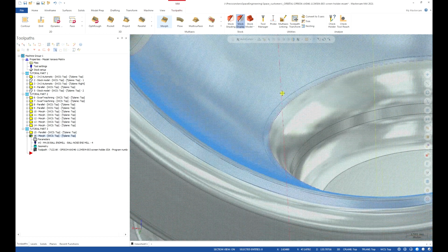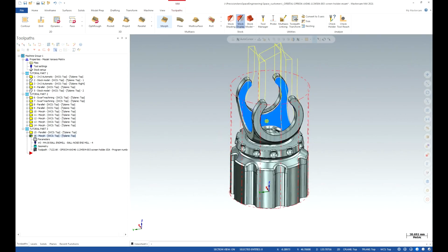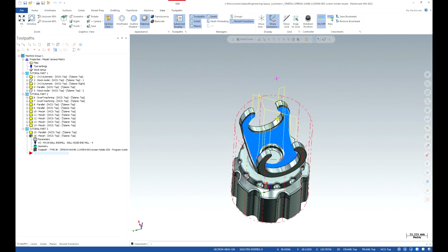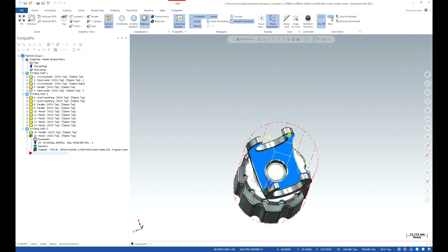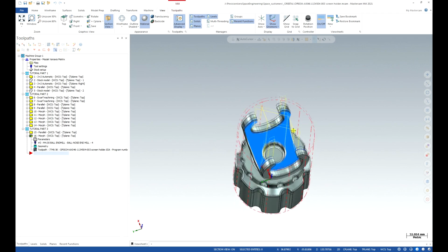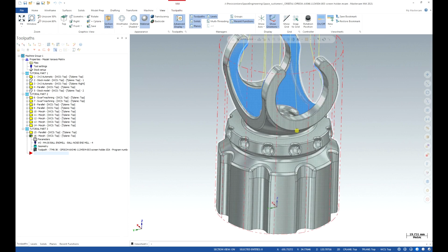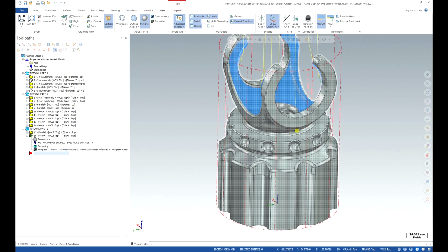Yes, I like it. We'll run the verify operation later. In the last toolpath, we were driving from the point, so every cut was from that point. Now we're going to use a different method of controlling the tool's axis, and we will drive the tool towards the point.